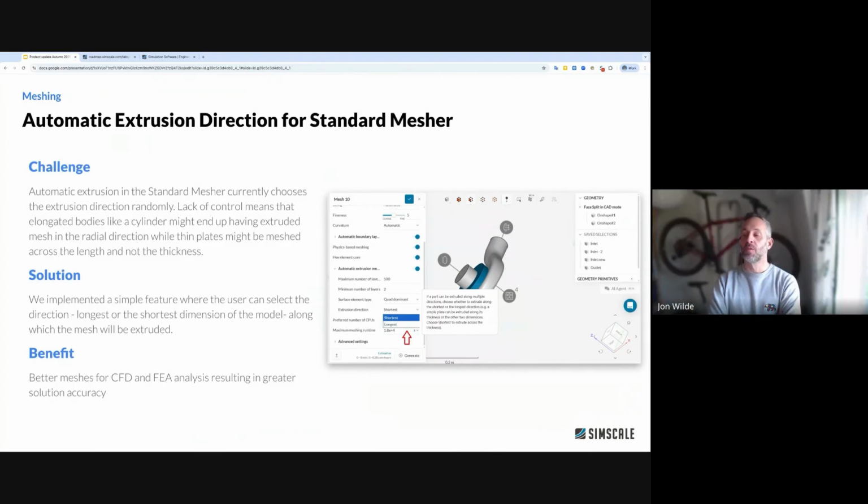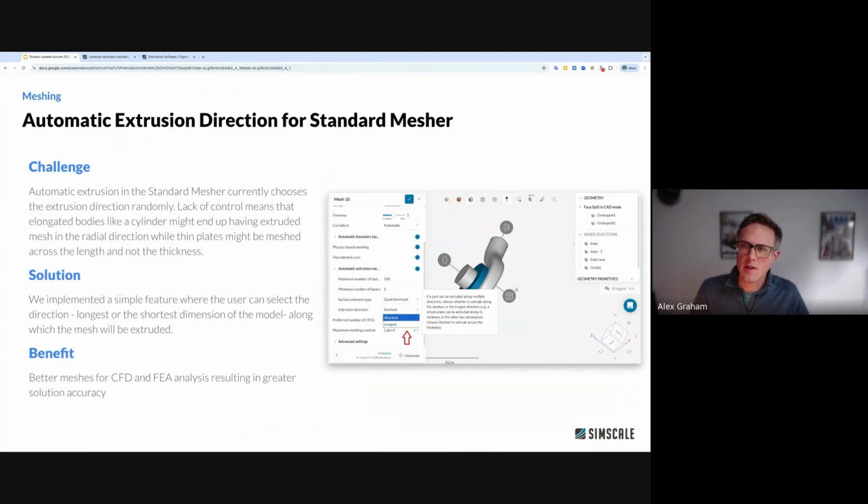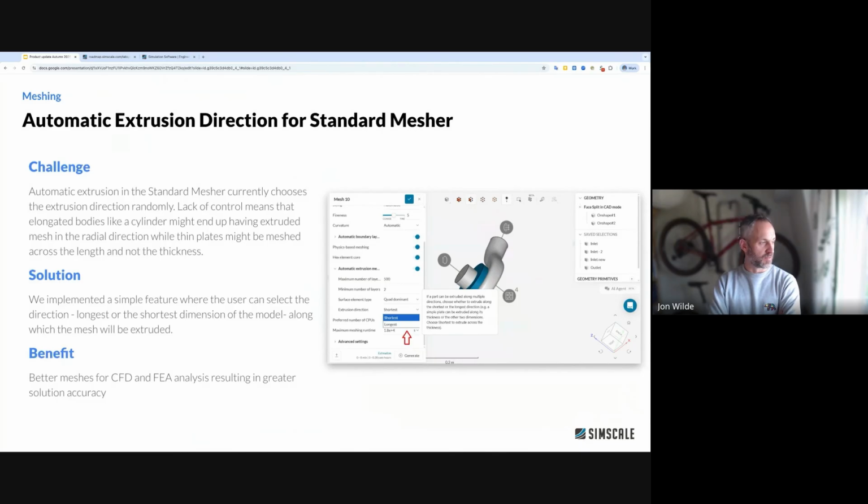Yeah, what you really want to do here is extend the inlet and the outlet. There's two different ways. If you extend the inlet, you should have nicely developed flow before the flow reaches the pump. Or if you had a velocity there, you could use a fully developed flow inlet. One of the two. Normally you don't do that though, because you have the flow being pulled out, so you have a pressure on the inlet, because you want to know the pressure gain at the outlet.